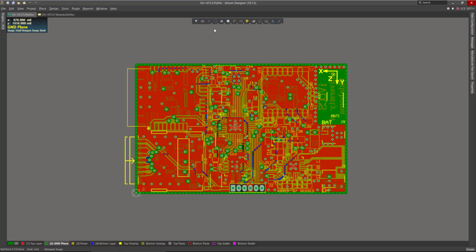And now some tool buttons will have a small down arrow inside their icon. Like here, you see these small arrows. That means there are more commands inside each one of these icons. This indicates that the tool button is a placeholder for several commands. To access the individual commands, right-click once on the tool button, and once the tool button expands, click on the lower level command to select it.